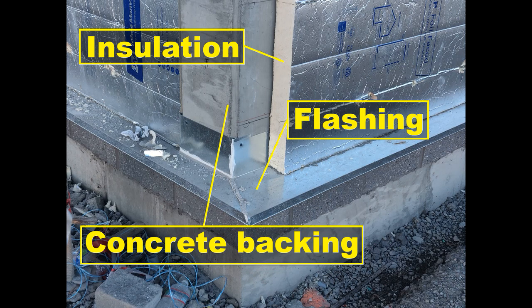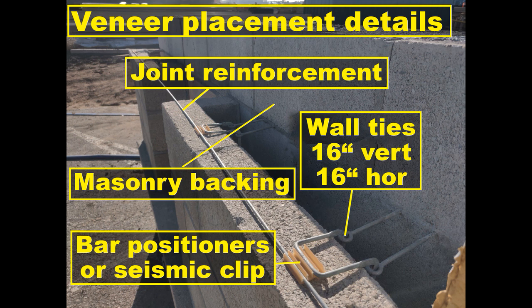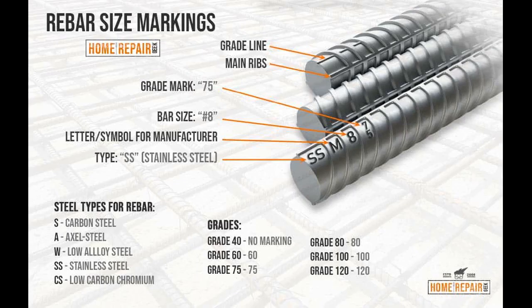Provide anchors and ties to connect the veneer to its backing in sufficient quantity to comply with the following. Provide at least one tie every 2 square feet at a maximum spacing of 16 inches in either direction. With solid units, embed anchors or ties in mortar joint and extend into the veneer a minimum of 1.5 inch, with at least 5/8 inch mortar cover to the outside face.